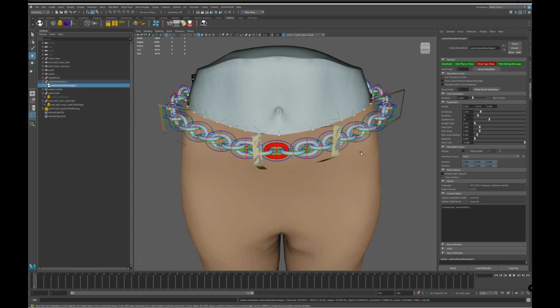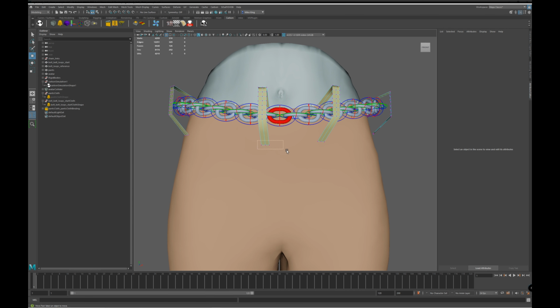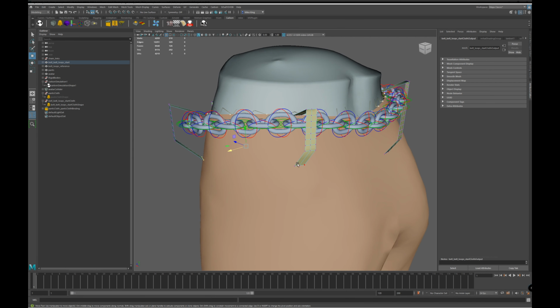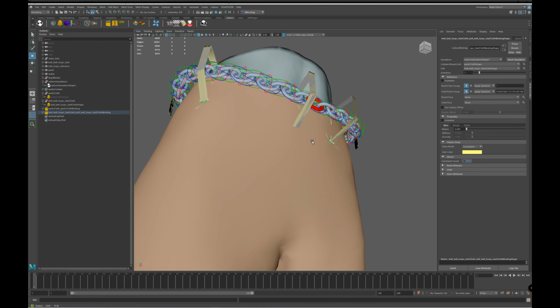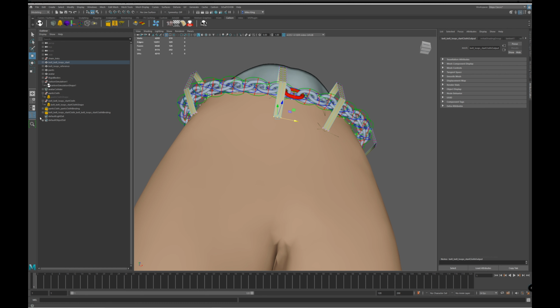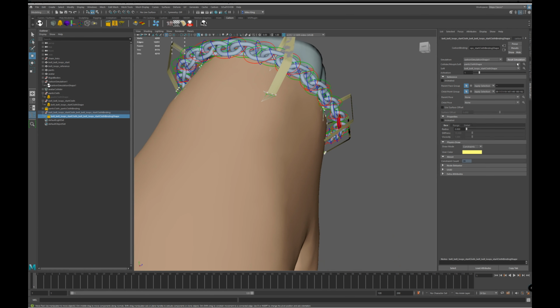Okay, next we need to bind the loops to the pants. We will use binding rather than stitching because there is no triangle alignment here to allow a nice stitch seam. First we go round and select the top and bottom vertices of each belt loop. Once we have them all selected, then we can click on the binding on the shelf and then add the pants as the other object for the binding. Now it looks like we might have missed that one, so let's select those vertices, hold Control and add to the existing selection. Now reset the simulation to confirm.